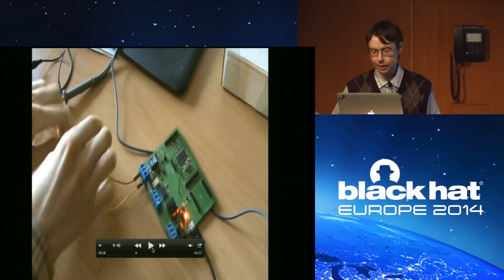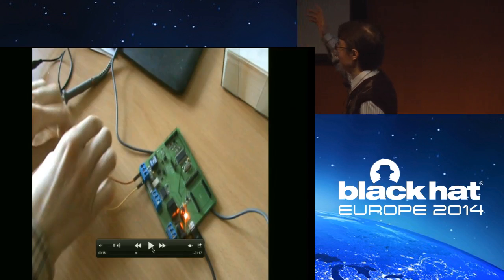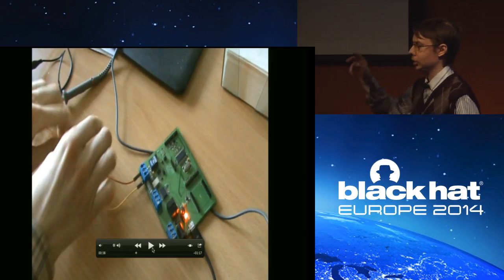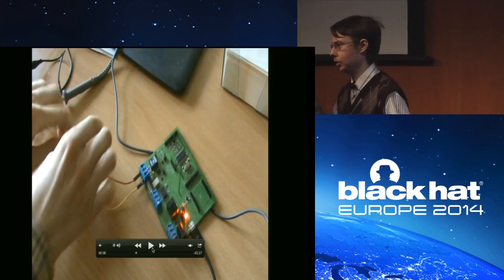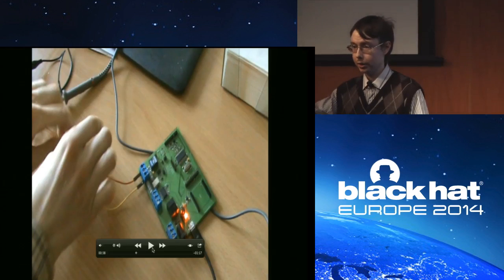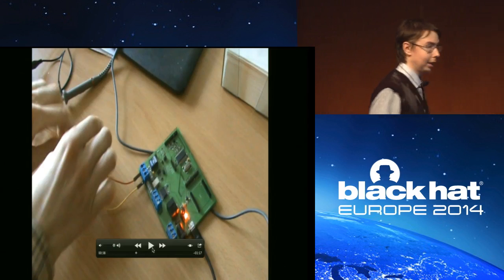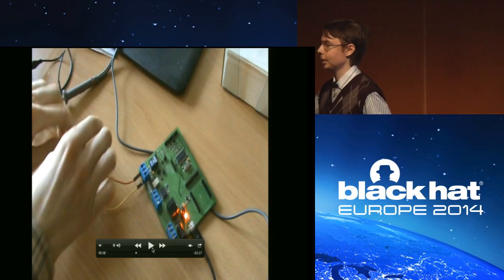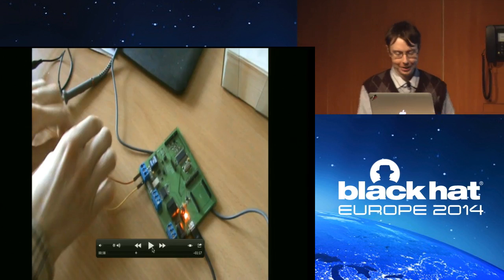And here is the ICS Cursor board. It's connected to the laptop with USB, and I just need to connect two wires to the current loop. I can do it directly by connecting via resistor, or by using silver needles. Just insert the needle into the copper wire. That's enough. HART is a very reliable protocol. It will work. It is designed for this.